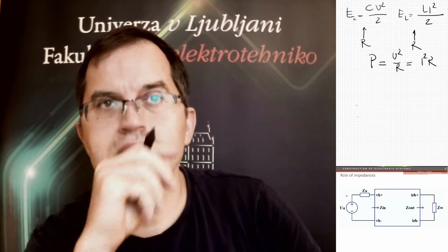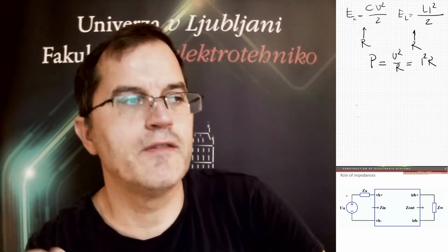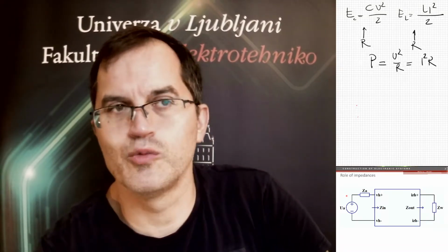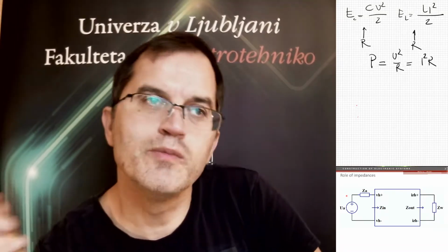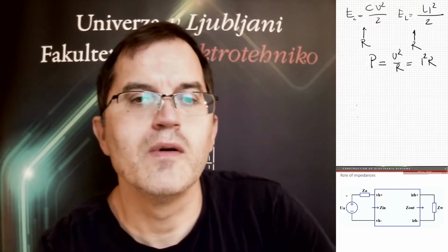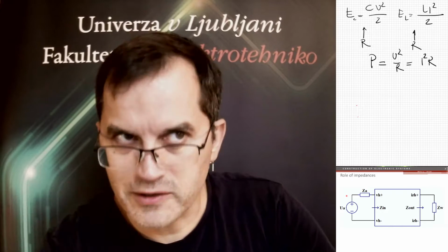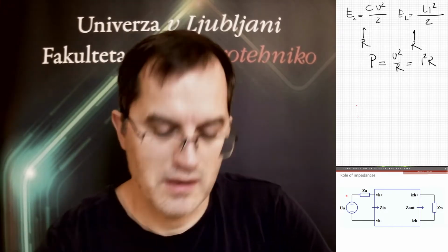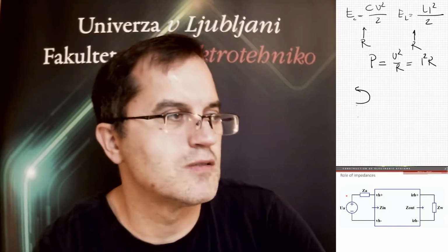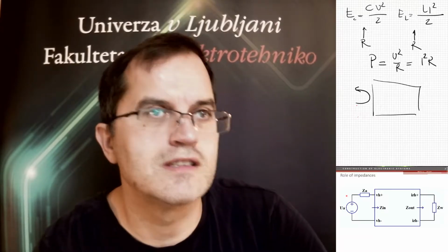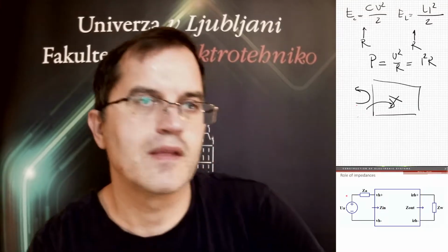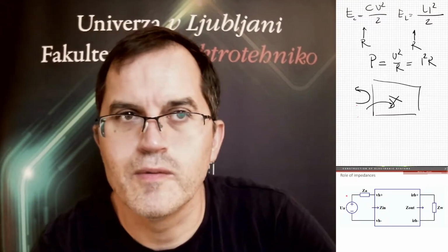Now, all that is possible only if you have the resistances included in any form. They could be actual resistors, or they could be losses in core or in dielectric. Now, the best filtering is by either reflecting the noise back to the source, if that's a filter. Imagine this is a filter. So we can reflect or we can dissipate, and the best is to do both.